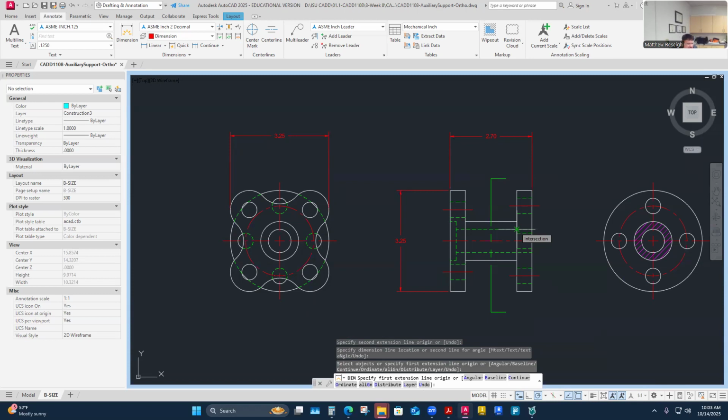Now I can start to break down each feature of the part. I always focus on the outside profile first, then I focus on the specific features and their size, or features of size as we might call it in GD&T land. There are features of size on this X plate part, but really I focus on its outer profile first before I deal with any holes.